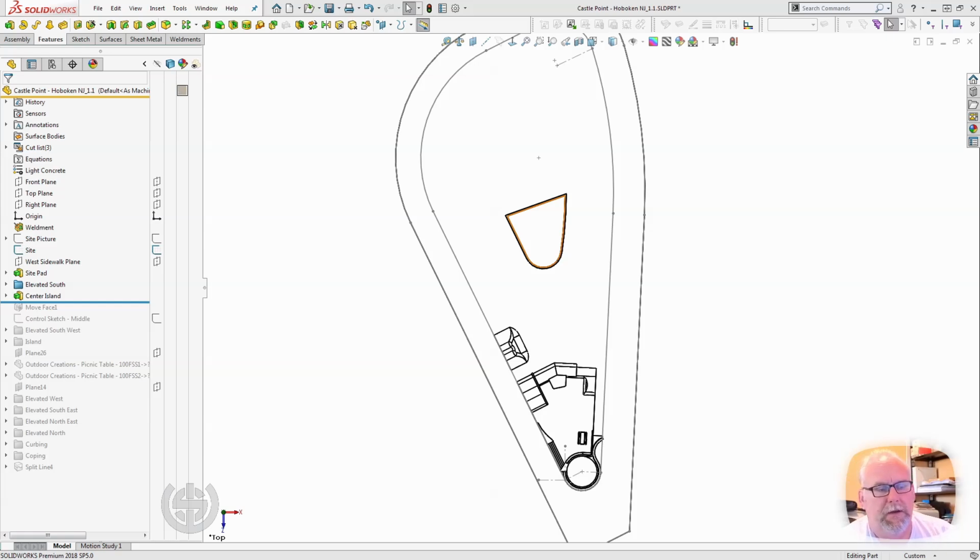Like I was looking at this one company, and I won't name them because I don't want to slander them, but somebody that had say over the park put round river rock in one of the beds, and I'm just thinking, man, in a couple months, all that stupid round river rock's going to be kicked all over the park. This is going to be everywhere. And that is because they haven't seen a park 10 years down the road. So if you're going to have planters, one of the things is the dirt inside the planter needs to be like 10 to 12 inches below the edge of the curb.